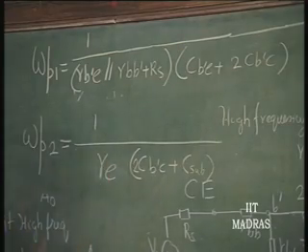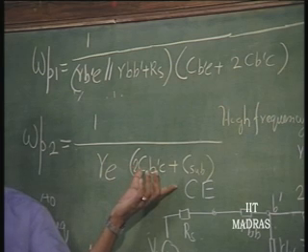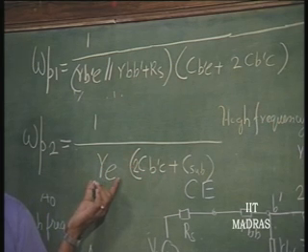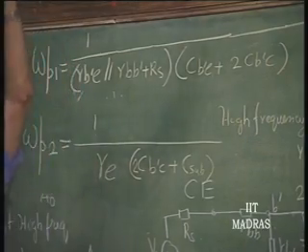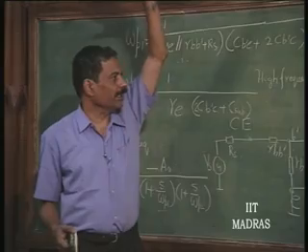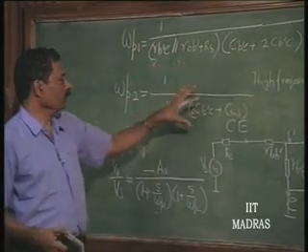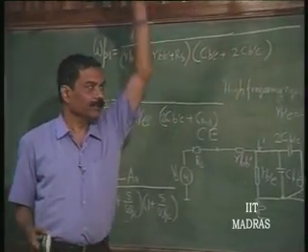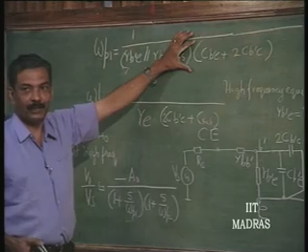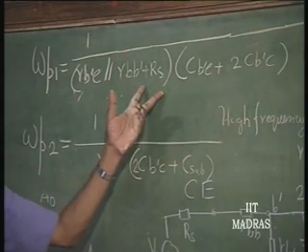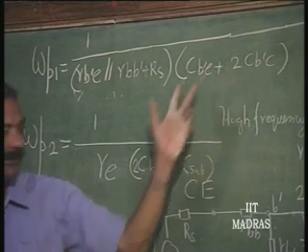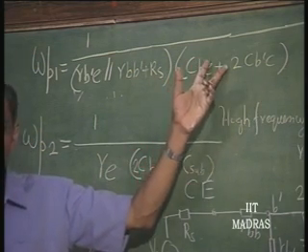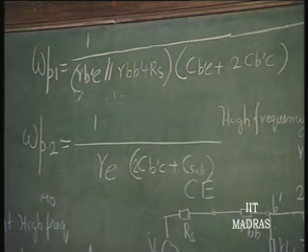So, you can see, not only is this capacitance low, now this particular resistance part is very low. Therefore, this frequency is shifted to the very high frequency end. So, this goes very high, this is the intermediate pole. This is still perhaps dominant, because this resistance is not very small, this capacitance is quite small, but compared to this it is still large, right, but it has been reduced from the earlier value,